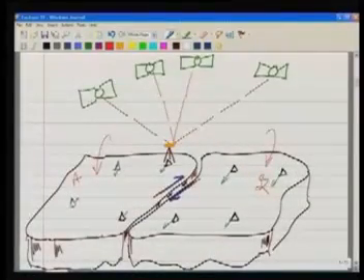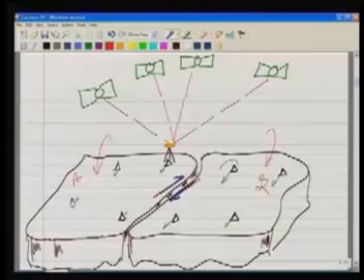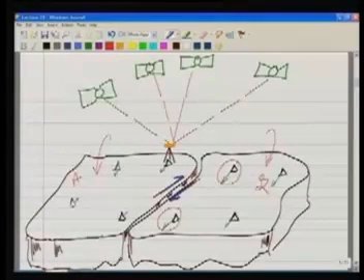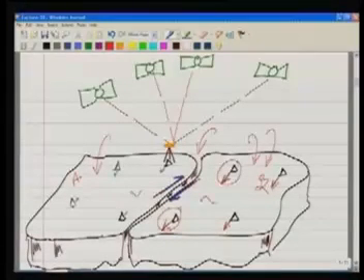So for example here, if there is relative movement, we will be able to measure how this particular station has moved over time. This green one here shows the movement vector. By knowing these movement vectors, it will be possible to estimate how the strains are developing over this particular land mass. And possibly it can be modeled when this particular fault will rupture, and there will be shaking of the land masses and the earthquake will occur. So this is one important application where GPS is being used.